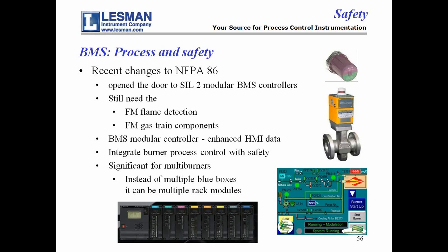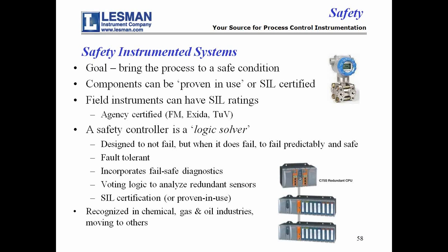The whole system typically involves voting logic because a lot of times it involves redundant sensors. They got to determine which of these sensors are working, and if a sensor goes bad, throw it out of the mix so that you're relying on the remaining sensors as valid sensors. Widely used in chemical, gas, and oil, but when you read the trade journal articles, you see that safety instrumented systems are probably going to move into other industries as well. So that sort of sums up our seminar today, or webinar today.